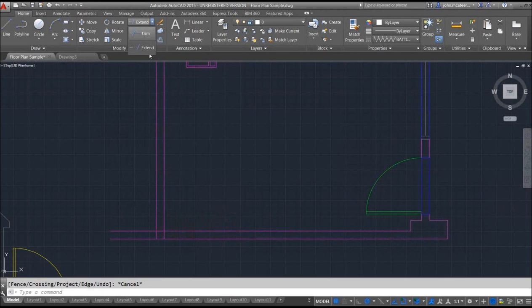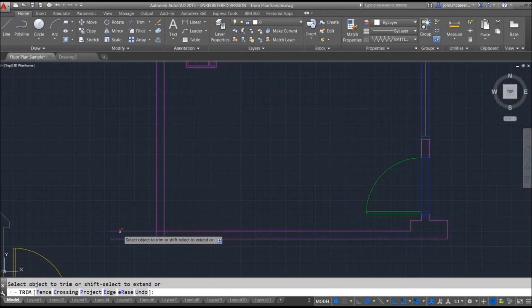Same goes for trim. When we're using our trim tool, when we highlight over it, it'll kind of show it in a gray. It's got a small red X there as well, the part of the line that's actually going to be trimmed. Okay, so no more surprises. That guy can also be turned off if you would like.